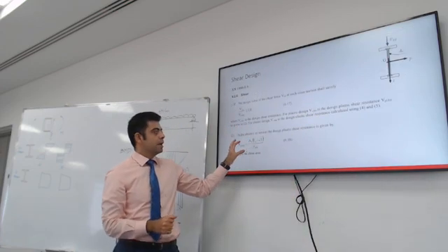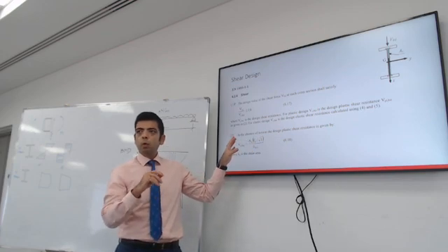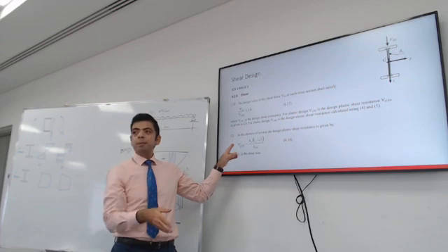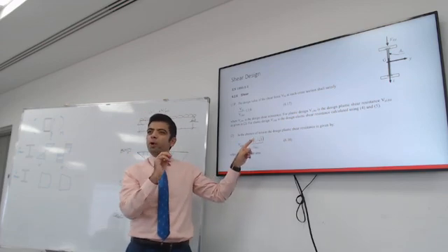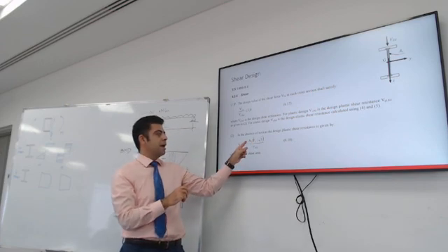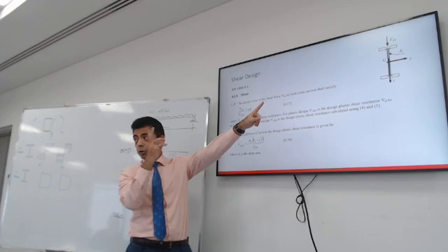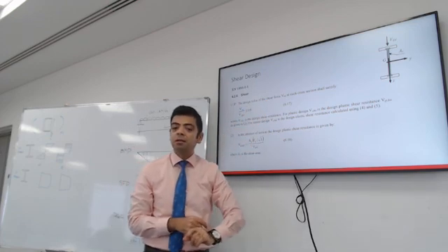So this formula is actually much simpler than it looks. When you simplify it, it will look something like this. The shear capacity is around 0.6 or 0.577 times AV, which comes from the area of the gray shaded area, multiplied by the yield strength of steel.